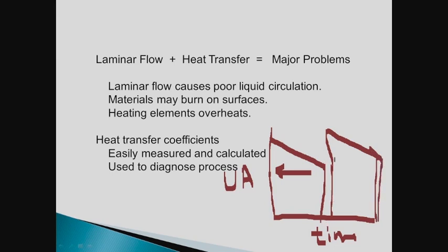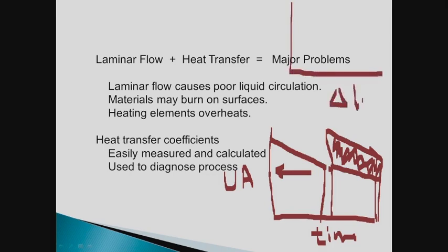Anyway, so the increase in performance that you got due to cleaning is this area in here. The cost of the cleaning was this area in here, the downtime basically. This is an improvement in performance. So the question becomes, you take this area here and divide by this area and plot that versus cleaning time or cleaning duration. And so you have perhaps an optimum point where this would be the optimum. Obviously, you want to maximize this and minimize this.